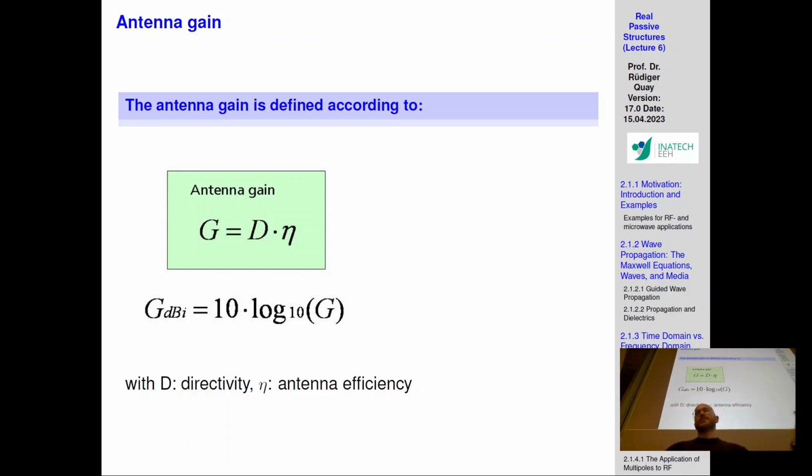An antenna is nothing like that. An antenna is a piece of metal. It's a conductor. It has losses. And so the gain, in a sense, is the ability of this antenna to accumulate the radiated EM waves in a certain direction, whilst also taking into account the losses, or the efficiency, of that antenna. And usually, ideally, efficiencies go up to 70% at most, and lie in the region of 50% or so for patch antenna applications.